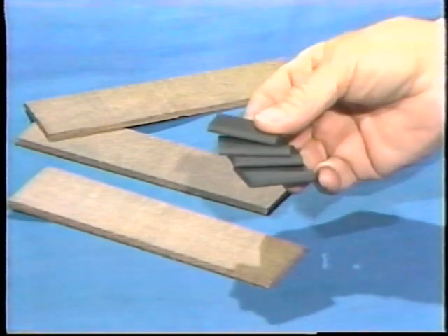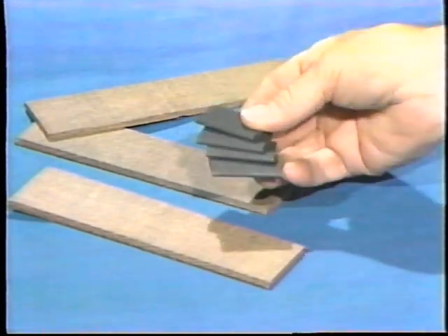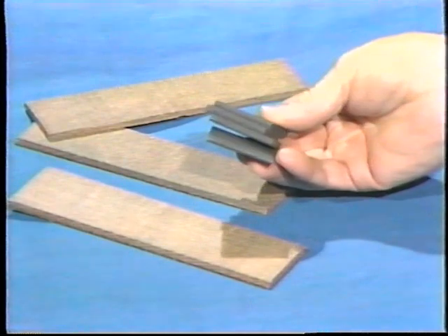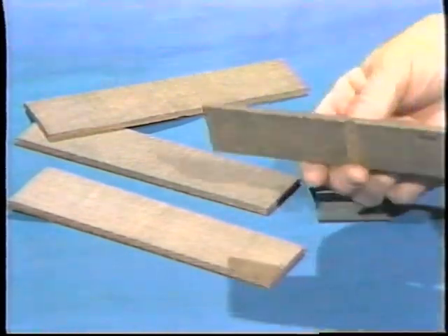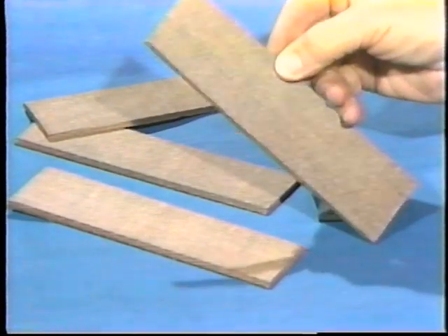Since they must slide easily against the housing, vanes are typically made from carbon or other low-friction materials, like these made from cloth that's been impregnated with phenolic resin. For small displacement applications, the vane-type compressor is a relatively economical unit. It has a low operating cost and requires a low starting torque.